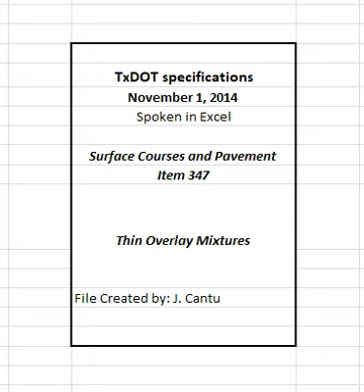Provide the engineer with electronic copies of all daily data files that can be used with the thermal imaging system software to generate temperature profile plots upon completion of the project or as requested by the engineer. 4.7.3.1.3 Thermal camera. Take immediate corrective action to eliminate recurring moderate thermal segregation when a handheld thermal camera is used. Evaluate areas with moderate thermal segregation by performing water flow testing in accordance to TxDOT 246F and verify the water flow is greater than 120 seconds.